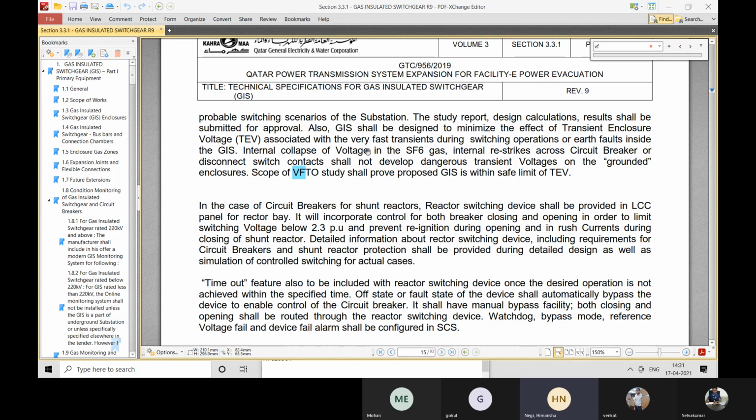And then in terms of transient requirement, there is no magnitude or surge specified, as Venkat clarified in the beginning for the VFTO. So you can put a generic switching waveform from the standard with some front time of 250, another is 2500, or in a different scenario, and then just inject it with maybe 1000 kiloamperes or something and just try to get a magnitude of the enclosure voltage. That's how it is done in CDEGS in a very simplistic way.